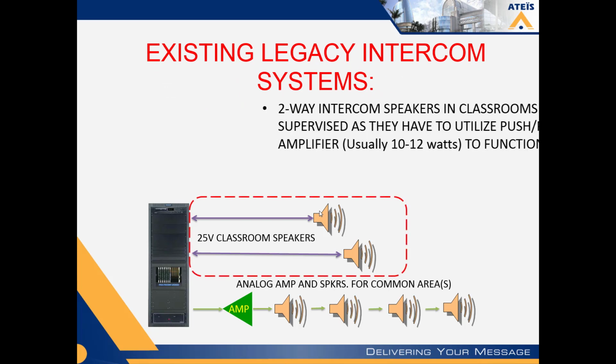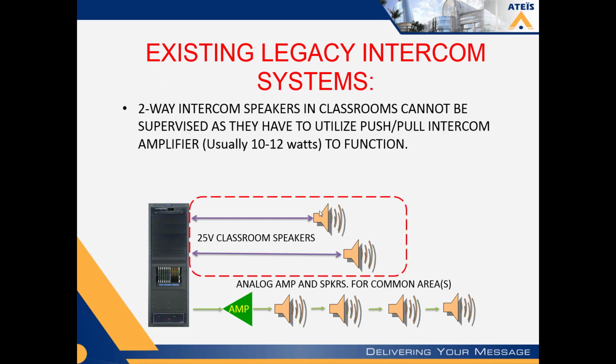Now, with these legacy intercom systems, the two-way intercom speakers that are usually in your classrooms cannot be supervised. And what that means is these circuits and speakers cannot be easily adapted and put onto a UL 2572 mass notification or emergency alert paging type of system like we're advocating here in this presentation. The reason is because these speakers are two-way intercom, or what we call intercommunications or talkback speakers.